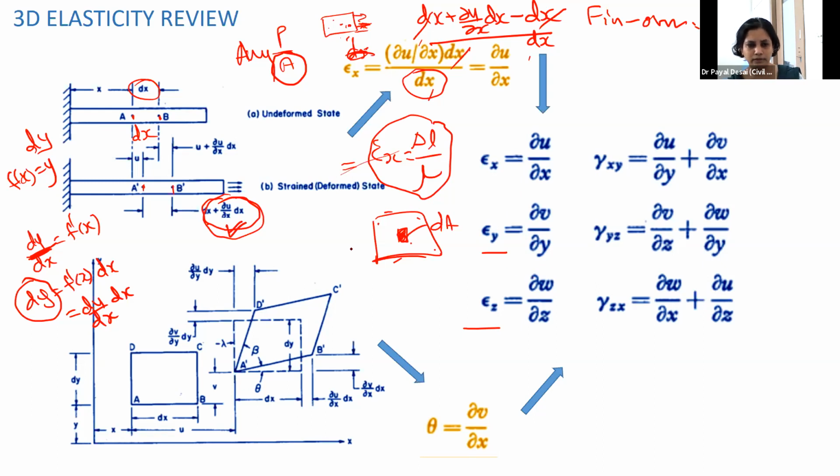And of course, as I discussed with you about shearing strain, it is a change in angle. When you apply shearing stress on top and bottom, and maybe vertical and downward here, this will result in distortion of the element. I am talking about one plane, but it can be applied to the other two planes also. And if it is in the x and y axes, here gamma xy is written.